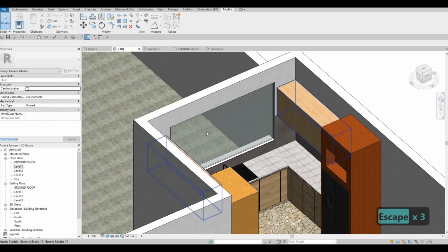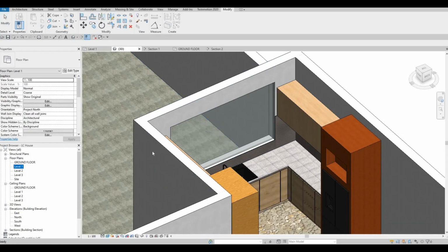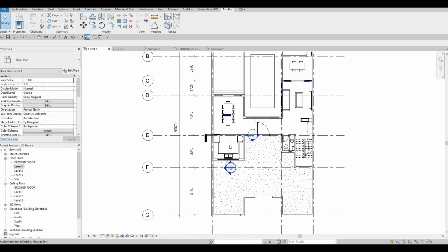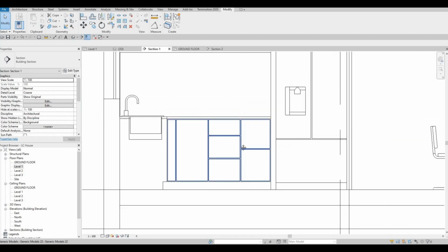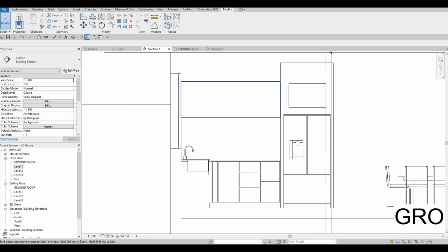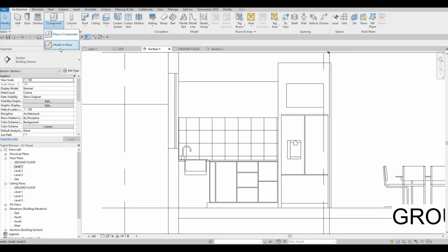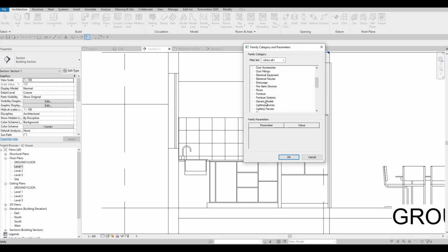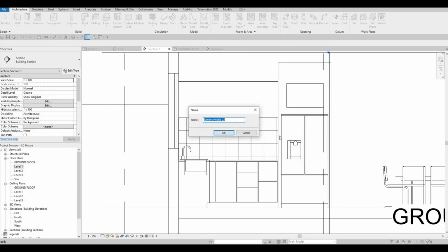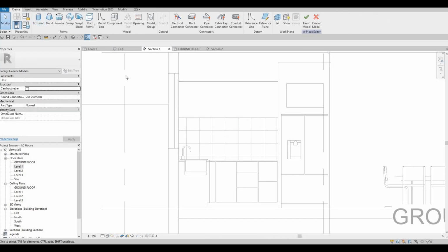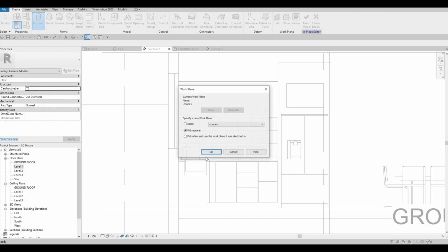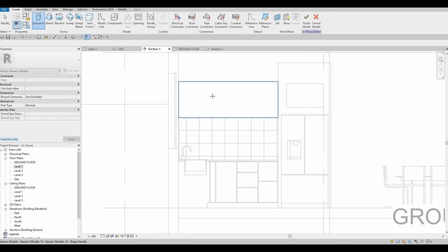door. So now, what I'm gonna do is let's go to level 1, and this is already facing on this side, so we could just double click. And then we need to click on architecture again, model in place, and then generic model. And then we need to set the extrusion plane on the top.